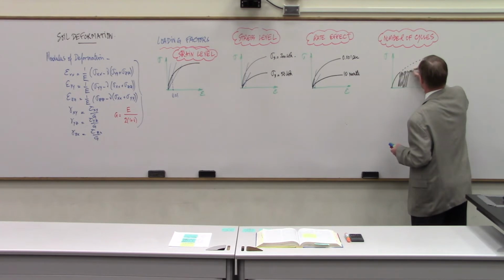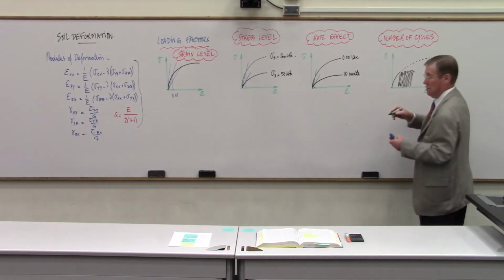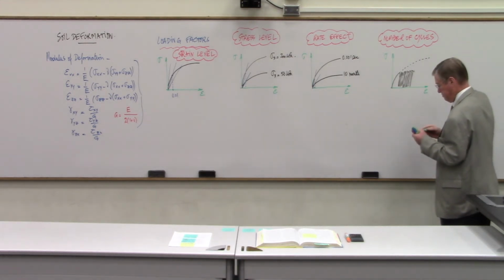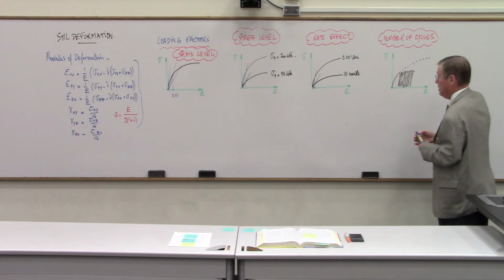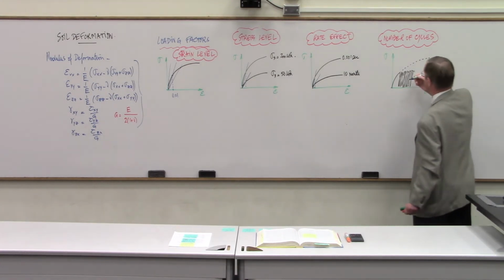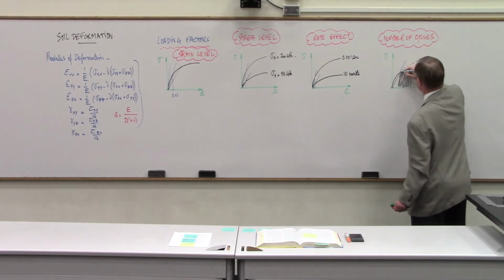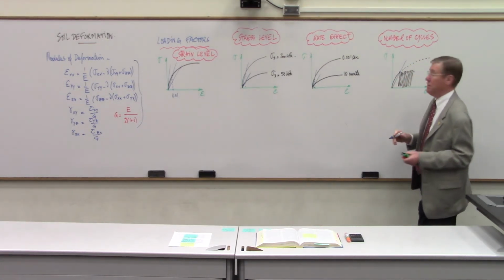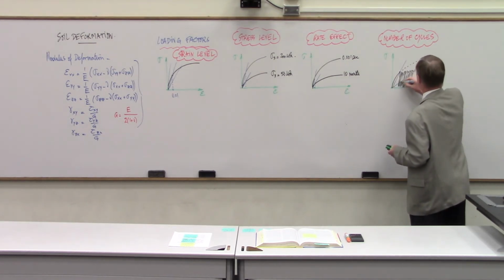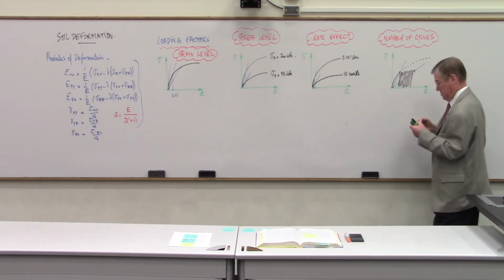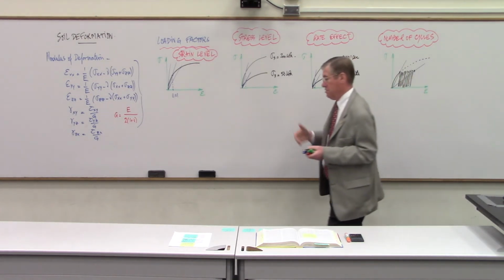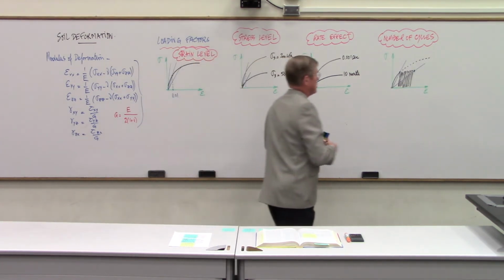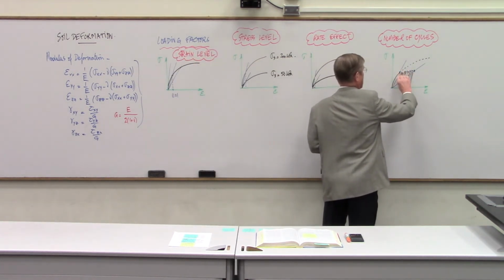Or I have a pavement that I'm going to be loading for 2, 5, 10 million loading cycles during the lifetime. And you can imagine then that the modulus associated with one cycle, like a building, boom, you put it down, you leave it alone, will be very different from the modulus that will be associated with 1,000 cycles, 1,000,000 cycles, and of course, in here, the amplitude, not just the number, but the amplitude of the cycle.